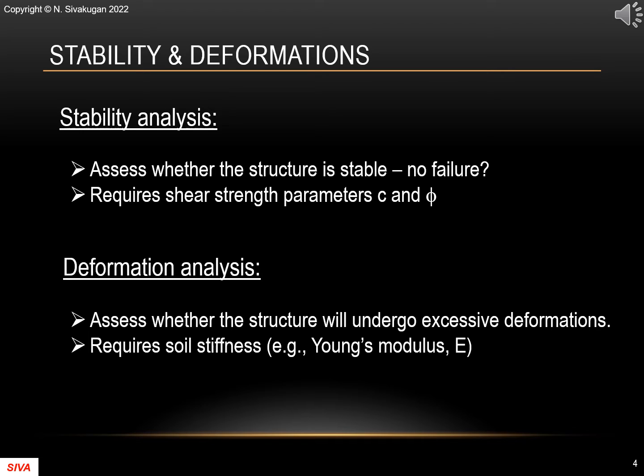When looking at stability, we need to ensure there is no failure. This requires the shear strength parameters, cohesion and friction angle. Determining deformations requires soil stiffness parameters such as Young's modulus.